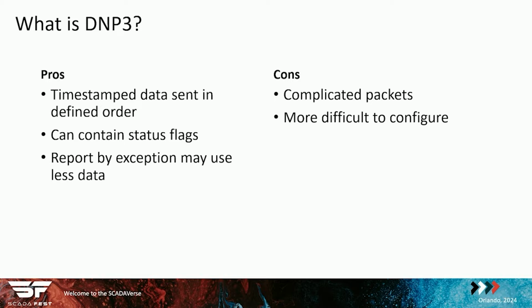And it's also more difficult to configure. There's a lot more options in DNP3. Modbus, you just basically assign data to the registers in your PLC, you read those, set up those IO addresses in VTScada, data comes in, you're good to go.